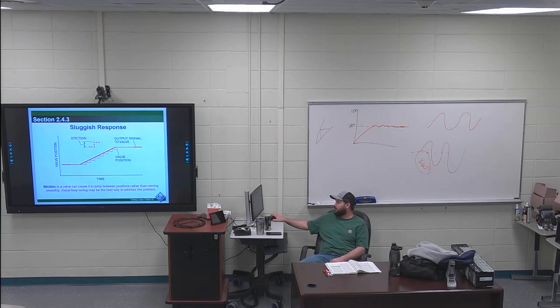So you can see, our valve position is not linear, it's stiction. You put a certain amount of pressure in there, and if the pressure on our control valve was 3 to 15 PSI, right? Well, maybe that control valve's not going to move if I go from 3 PSI to 4 PSI. The valve doesn't move at all.